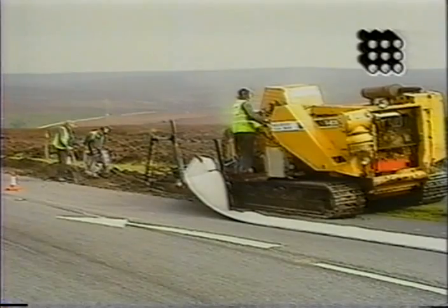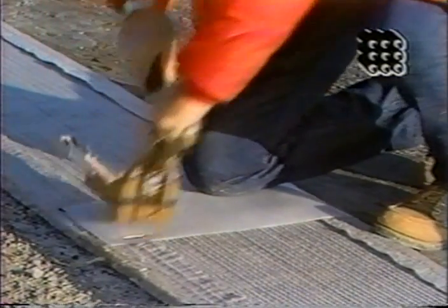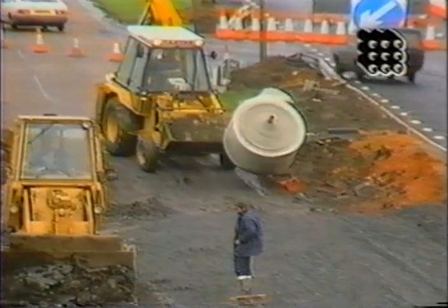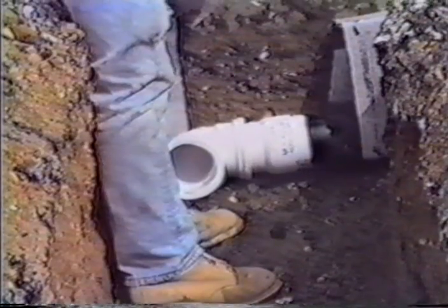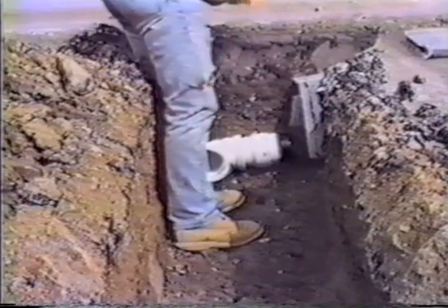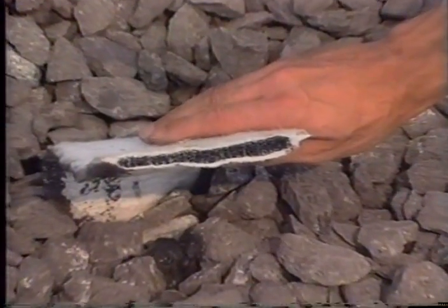These materials consist of a geotextile filter separator bonded to a stiff or flexible drainage core. All have high flow capacities when they are not compressed, but differ in their compressed state. Most manufacturers quote the flow rates under load and at various gradients. Geocomposite drains are used in three main ways: as edge drains for pavements and interceptor trenches adjacent to roadways, as sheet or blanket drains, and as vertical or wick drains.